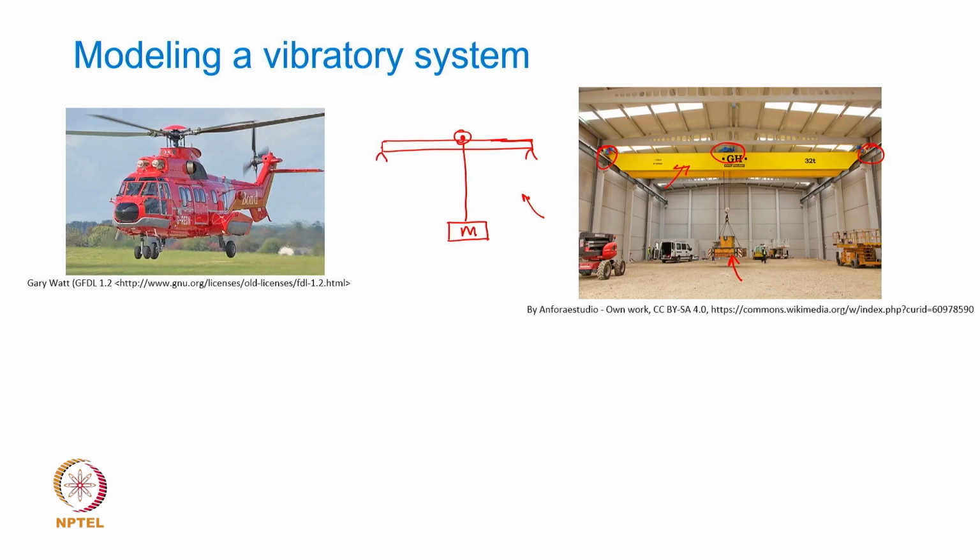Okay. Now, how do I model this as a single degree of freedom system? The wire rope here, what you notice, itself can act like a spring, because the wire is not an absolutely rigid one, and under the action of such a heavy load it can stretch, and that stretching means that it is a compliant member and may have certain stiffness.